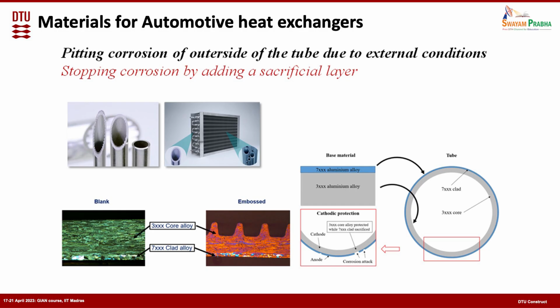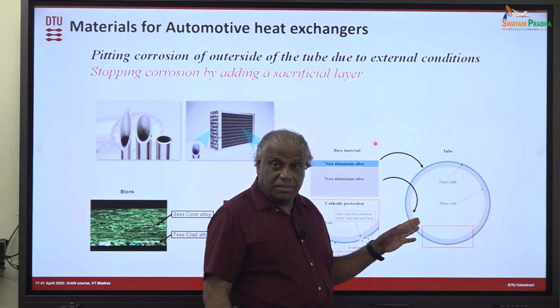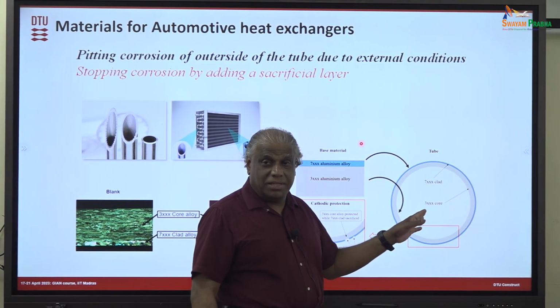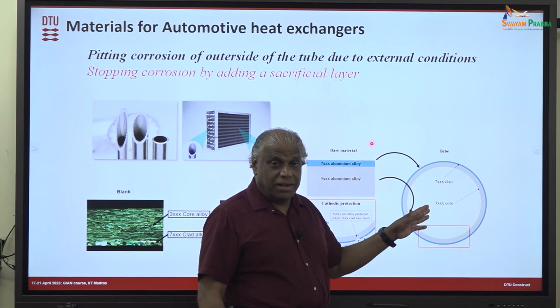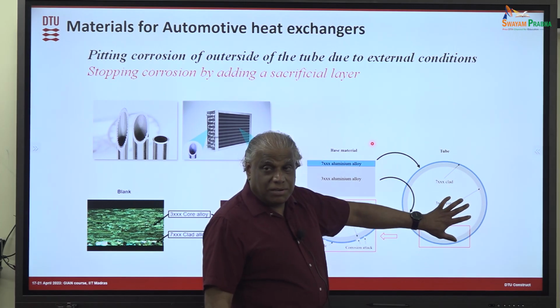200 micrometer is the wall thickness of the tube used as heat exchanger tubes in the automotive industry. Now the automotive industry is asking whether that can be reduced to 100 to 150 micrometer. When you have a 100 to 150 micrometer thick tube, what's the problem? This is a heat exchanger tube, and the coolant is passed through it. They don't worry about corrosion inside the tube, because the coolant always has corrosion inhibitors, unless you add water. You don't worry about the corrosion inside.